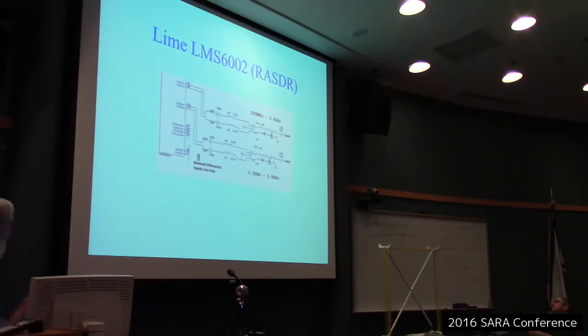And another one I'm looking at, the LimeSDR chip, is an example of differential signaling, and their schematic. This was actually of the BladeRF board, because I had the schematic handy at the time, and I didn't have the Raspberry schematic handy, so I grabbed that and cut a little piece out and put it here. But you've got some kind of balun here to convert from your single-ended input to differential, and then it's differential going into the Lime chip because it's inherently differential.